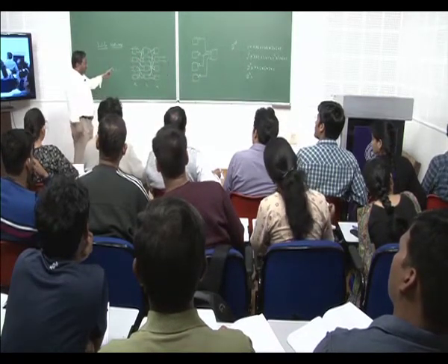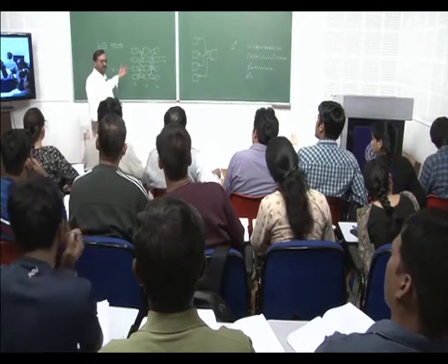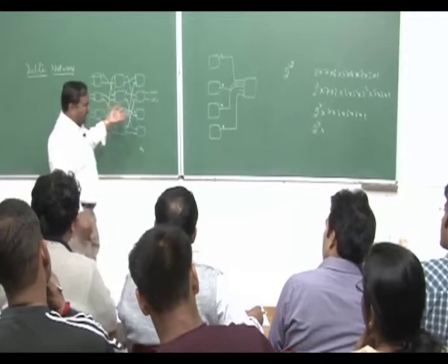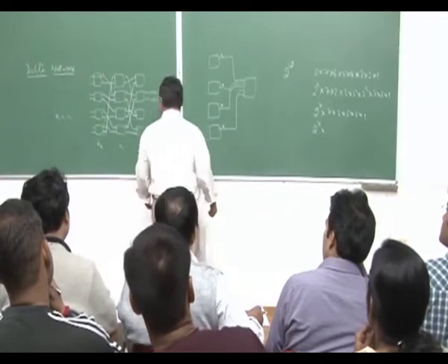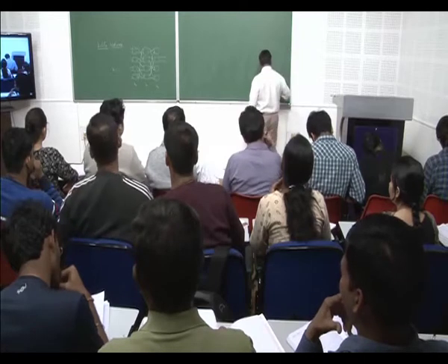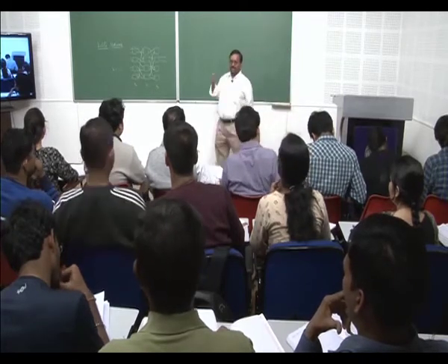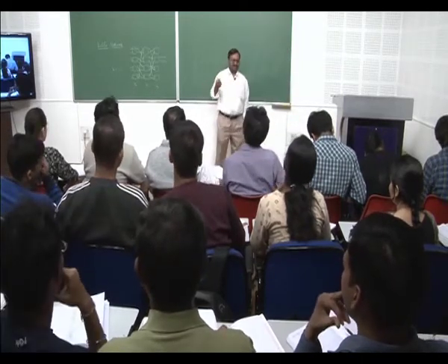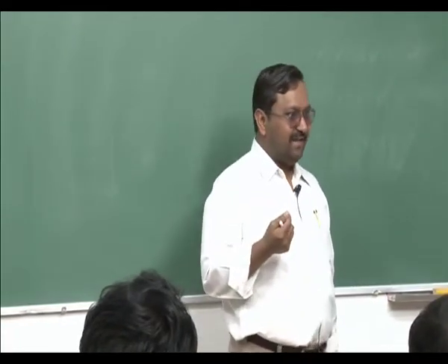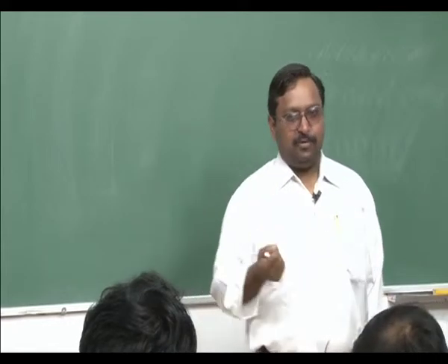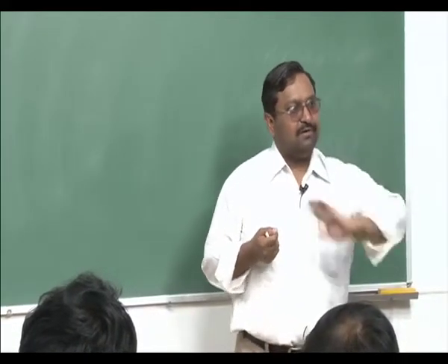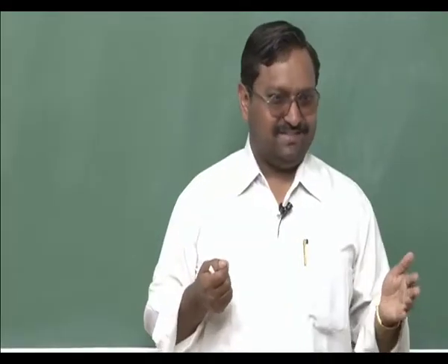So, now coming to the actual definition. Now, this is with 2 by 2, all life is very simple. Want a simplified version? I think go with a Benes network. The most important thing is you have figured out how to create a delta network. Make sure you always create a demultiplexer tree, and the inputs to a switch should always come from the same output number from the switches in the earlier stage.